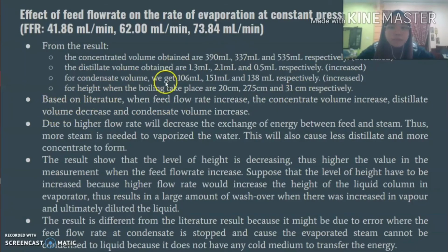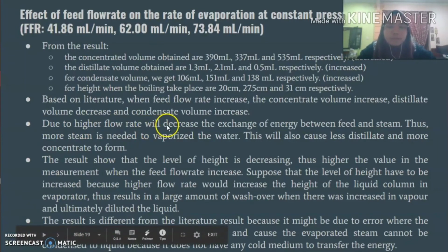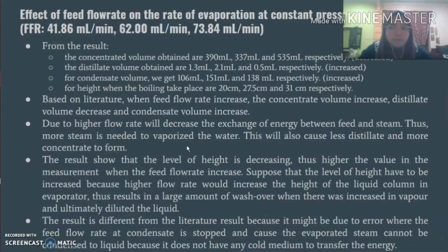Based on the literature we get, when feed flow rate increases, the concentrate volume increases, distillate volume decreases, and condensate volume increases. When the flow rate increases, at the same time it will decrease the exchange of energy between feed and steam, and therefore more steam is needed to vaporize the water.